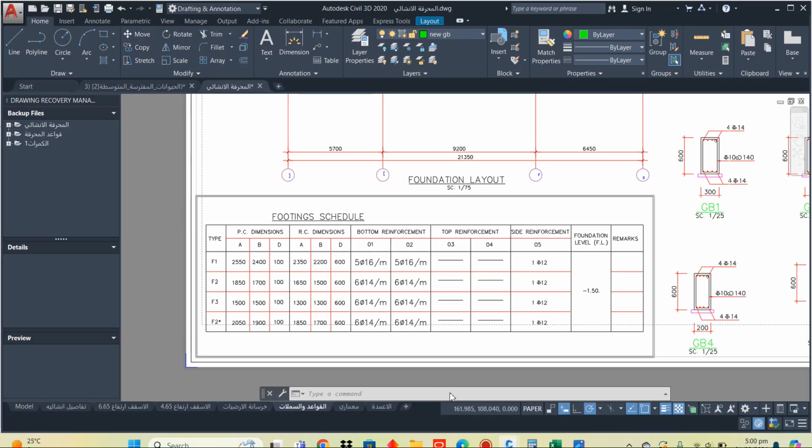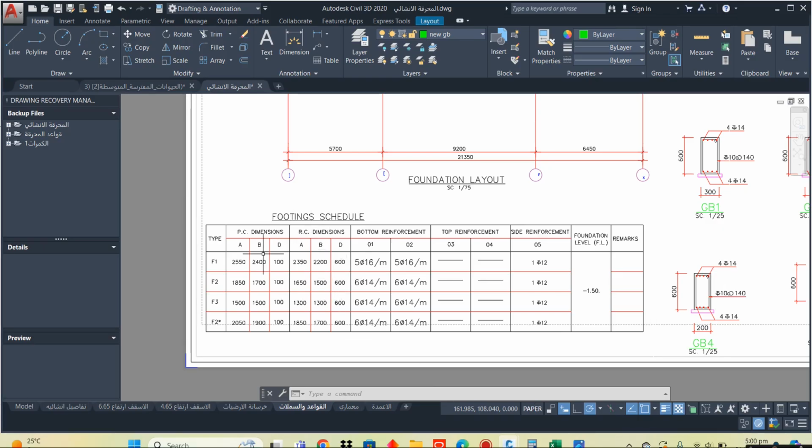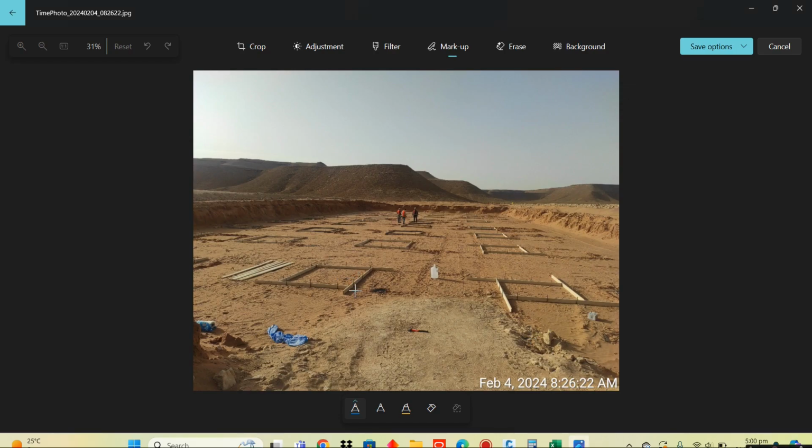Because I have already told you that we have to calculate this formwork in meter square. So this is 2.5, this is 2.5, so I have multiplied with 2 so I will get both sides. Okay, so this is 5 meter total.